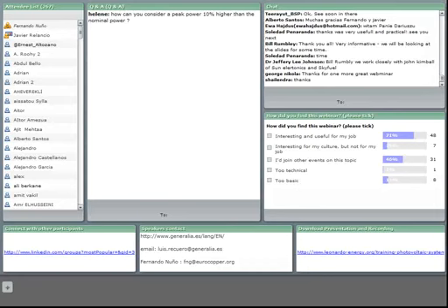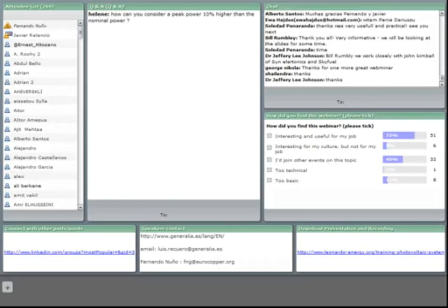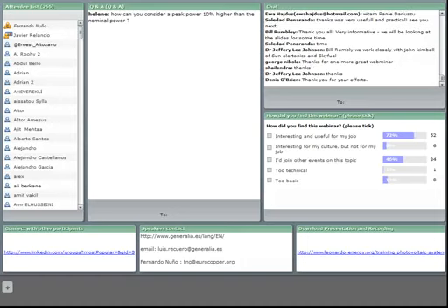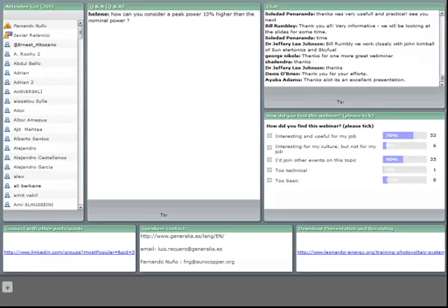So a good practice is installing 10% more panels than the nominal power we are considering for the inverter. So for example, if we have a facility of 100 kilowatts nominal power, this will mean power in the inverter of 100 kilowatts, but installing 110 kilowatts of power in the panels. I think that with that, all the people can have it clear what we meant.